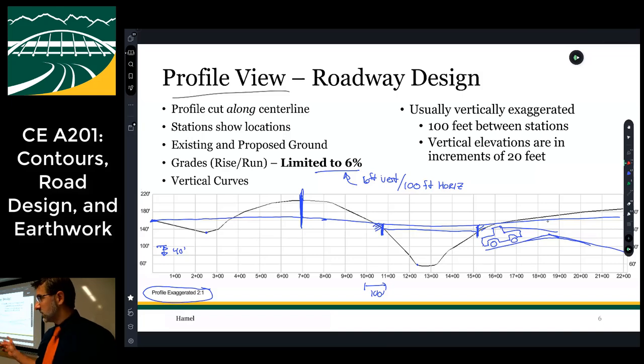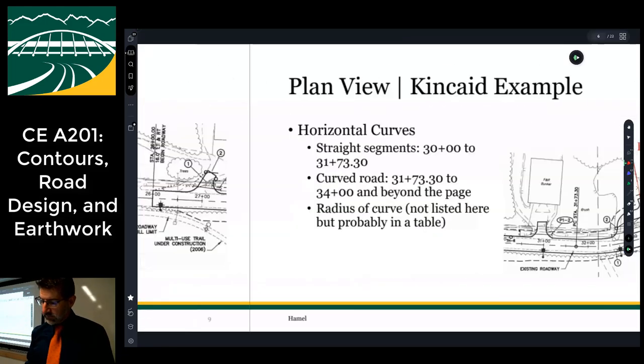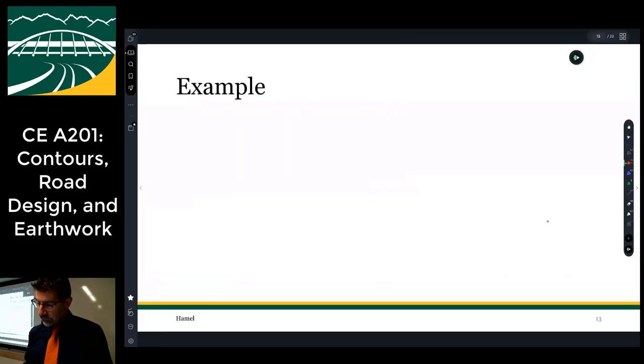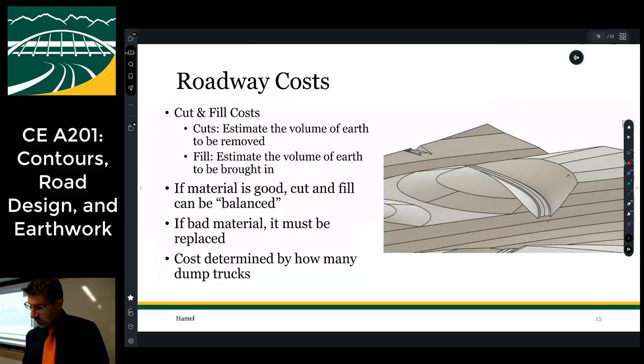But in Civil 3D, you can do that. You can create a section and run it along the horizontal path in both the horizontal and vertical directions, so it will cut through the land basically as you would do in real life. But the result of that is that you end up being able to calculate this area of ground, basically the volume that you have to cut, right?